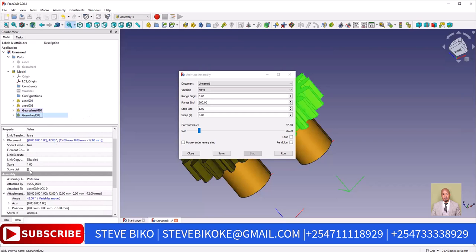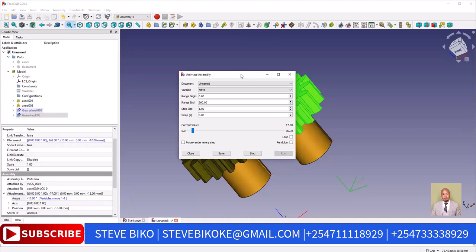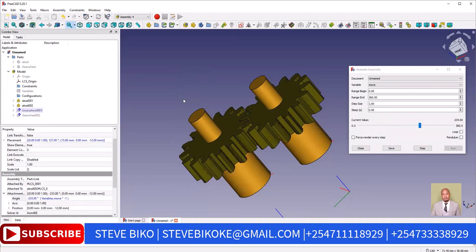Then we go to angle. Then I type multiplied by -1. Then okay. Then I run it again. Then now we have a moving gear wheel in Assembly 4 workspace. And there we've achieved our objective.